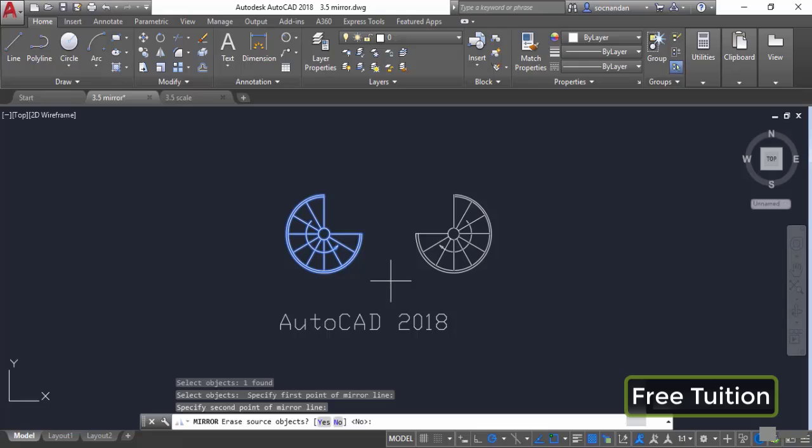And now click here and now look at the command line. So now it prompts you to specify whether you want to erase the source object or not. So we don't want to erase this source object. So I'll select no, the default value, and simply press enter. So here we have the mirrored image.